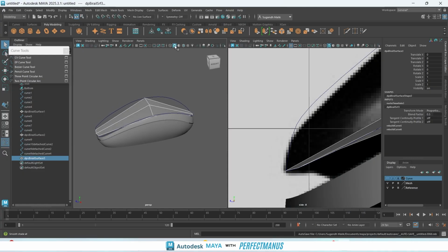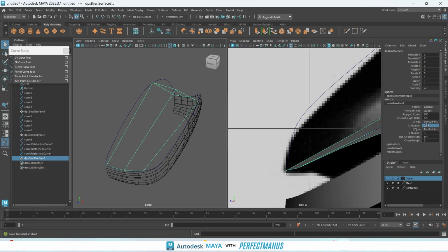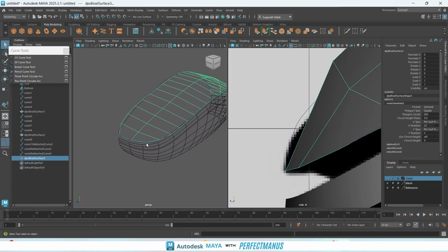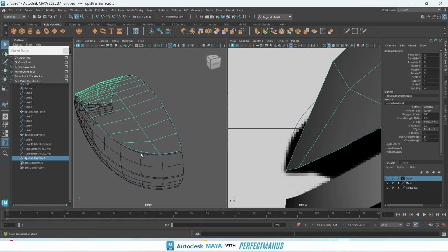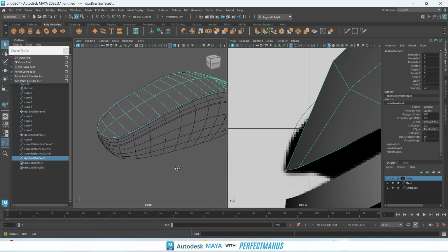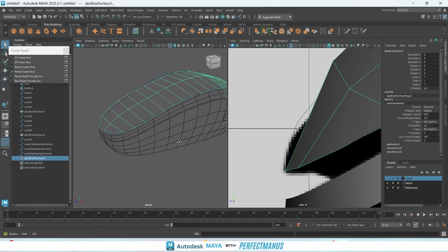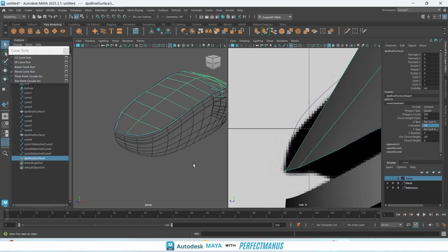But now before we decide how many divisions it will have, we need to see our other meshes, in the wireframe mode. Because when you decide its divisions, it should be somewhere matching with the other ones also. So by again coming here, increasing the divisions, you make sure it has as many divisions as number of sides. So 1, 2, 3, 4, 5, 6, 7, 8. It's getting much harder now. What we can see is 1 and 2, the edge points get deducted. So instead of 20, it left 18 by removing this point and this point in our counts. Then we can remove this one also and this one, so it's left to 16. Then this one and this one is left to 14. So instead of creating 20, we have to create 14 for it to match the similar number of divisions.